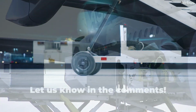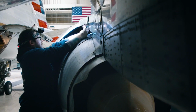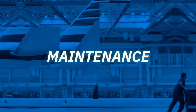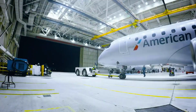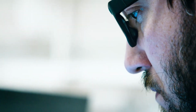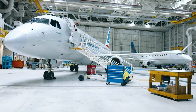A pivotal portion of this regulation is the first section in Subpart J, 14 CFR Part 135, Section 135.411, Application. This section specifies that aircraft having a type-certificated passenger seating configuration of 9 or less may be maintained in accordance with the maintenance manual provided by the aircraft manufacturer. Those aircraft having a type-certificated passenger seating configuration of 10 or more seats must be maintained in accordance with a maintenance manual written by the air carrier and must then be submitted to the FAA for approval.